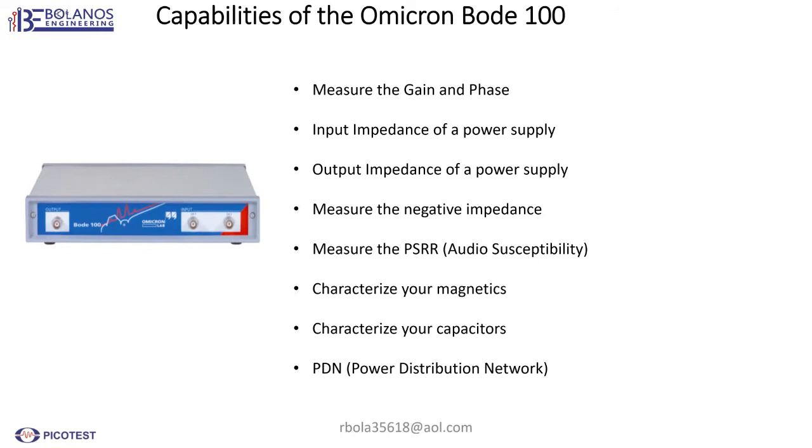Starting on top, one of the first measurements that one will do is measure the gain and phase. What you're really doing is measuring the stability of your power supply. This is very important. It's a must. Usually the gain and the phase are specified in your requirements and specifications.